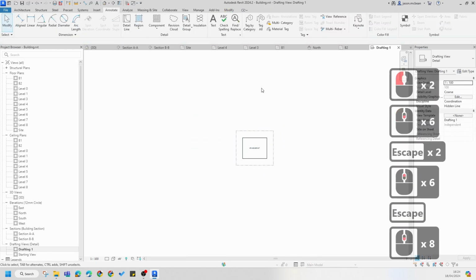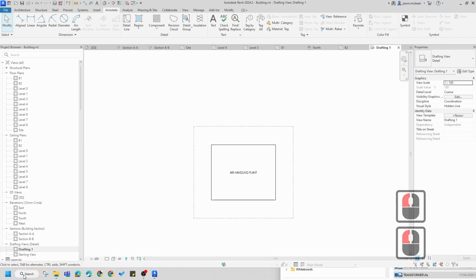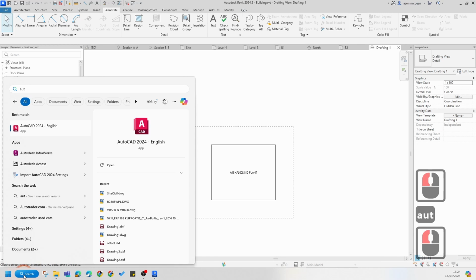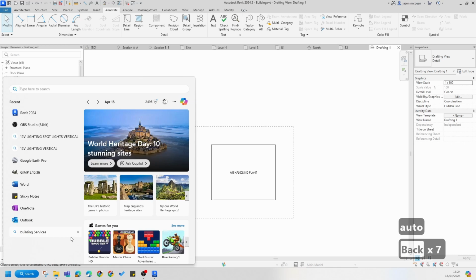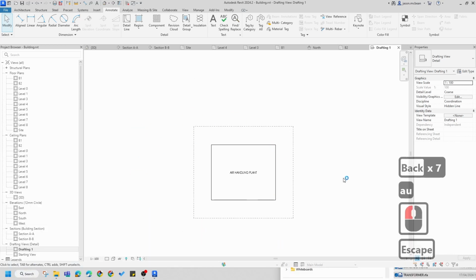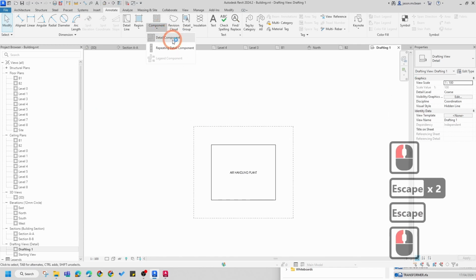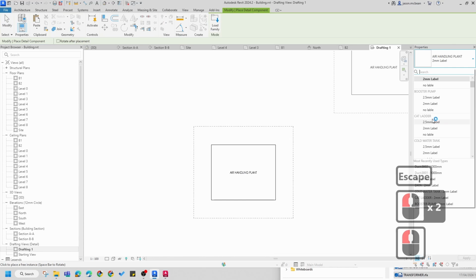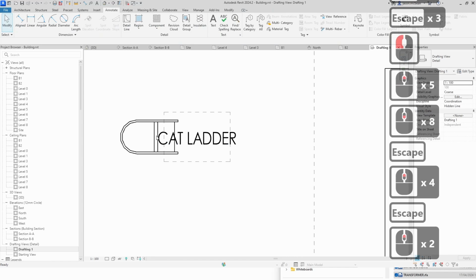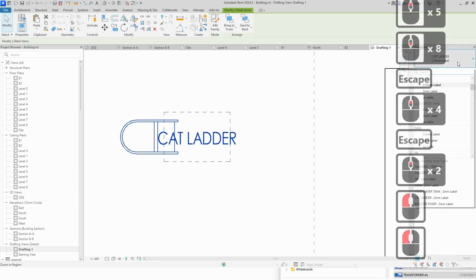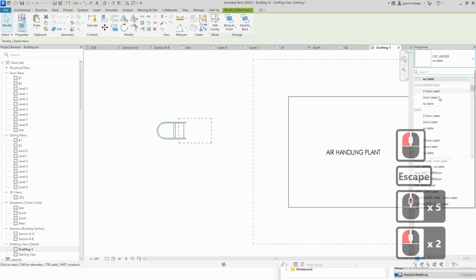So I've taken all the services drawings that you were given in AutoCAD. So let me open that file very quickly. I've gone and recreated all of these files for you in this project file, so you can start dragging and dropping them in here. Detail component, they've all been named accordingly. So a cat ladder, for example, and you notice they come in with labels. Now that text does work in some instances, but if it doesn't, there's a type associated to it that you can switch down. It'll be no label, it'll have no text. And it'll have 2 sizes of text as well.